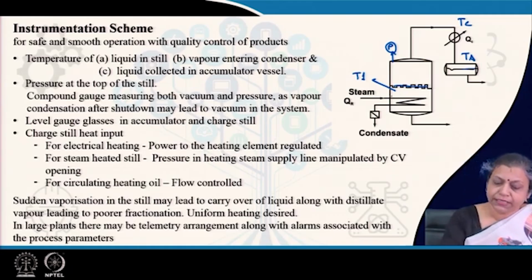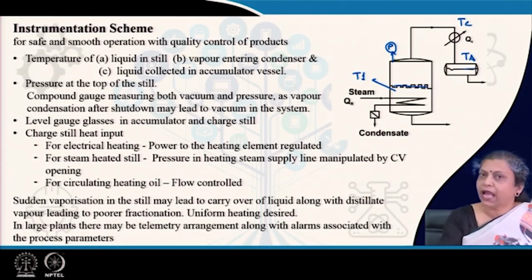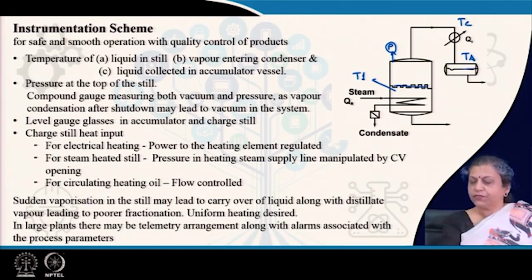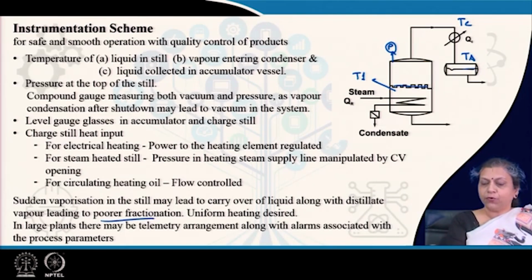Therefore, the heating rate should be controlled, it should be as uniform as possible, because if suddenly a huge amount of heat is given and there is a lot of vaporization, there is every chance that the vapor will entrain some amount of liquid and take it along with it, and that will reduce the efficiency of the distillation. It will result in poor fractionation. So, uniform heating is very much necessary, and the heating rate is necessary because that tells you the duration of the startup period and also the rate of distillation.